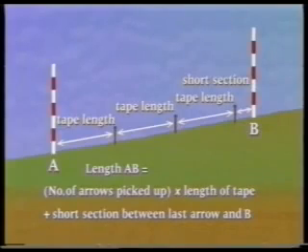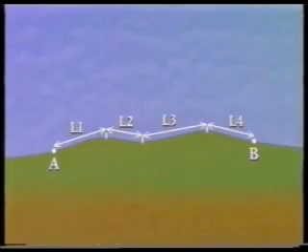This technique of ranging works well if the ground slopes constantly between the endpoints of the line, but often this is not the case. For example, the ground may change slope several times. In this case, the length along each slope should be measured separately. Sometimes there is a severe drop on the line. In this case, a technique known as stepping can be used.